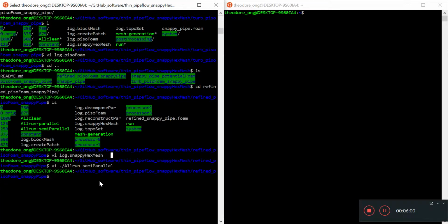So yeah, do make sure, at least for parallel, the best way is to make sure the computer is undisturbed for whatever amount of time you need. Unlike running in serial, where I think if, let's say, it stops at 250, you can just easily continue using the run latest time in the control dictionary, right?